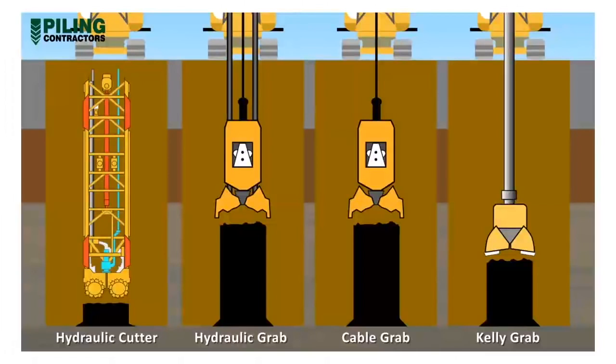This grab type is rigidly suspended from the base machine, whereas the three previous types are rope suspended. The Kelly grab can provide reasonable excavation forces and vertical control but may not be as fast as suspended grab excavation. Typical diaphragm wall widths are about 600 mm, 800 mm, 1200 mm, and 1500 mm. Other sizes can be used for special requirements.